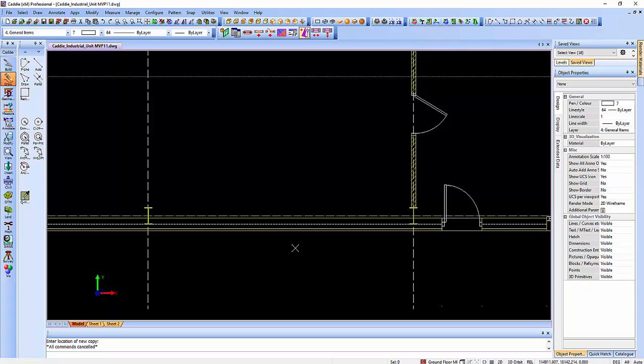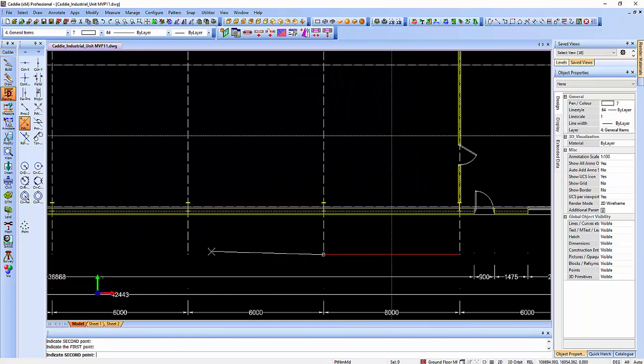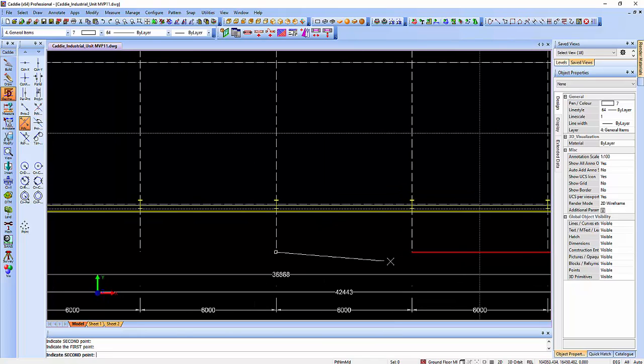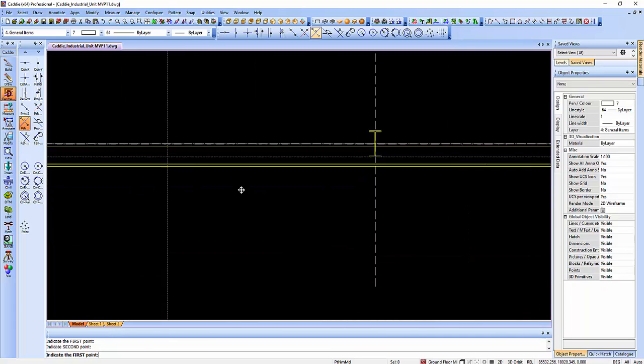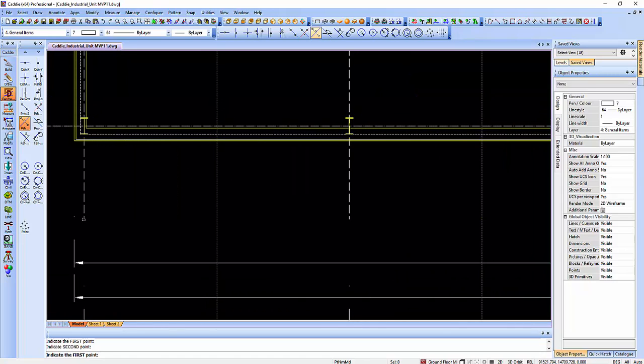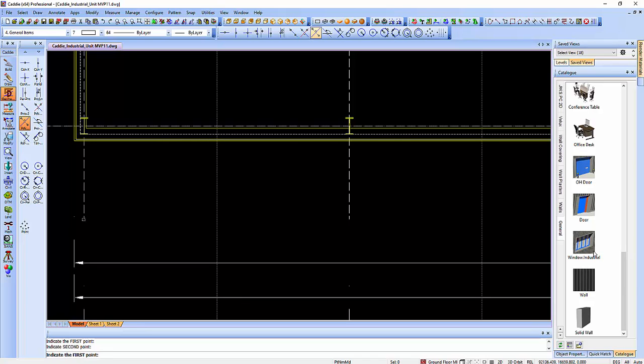And for the overhead doors, we'll use a similar operation here, but we don't need to divide it into 4. We'll simply use the one on the standard menu here, which subdivides between 2 points. So there we are. That's given us the setting out positions for the centres. So you can just drop those in very quickly. And then choose our overhead door, and again, just getting out far enough so we can see the AEC dimensions, come down our catalogue, go for the industrial overhead door, bring it in, and drop it in.